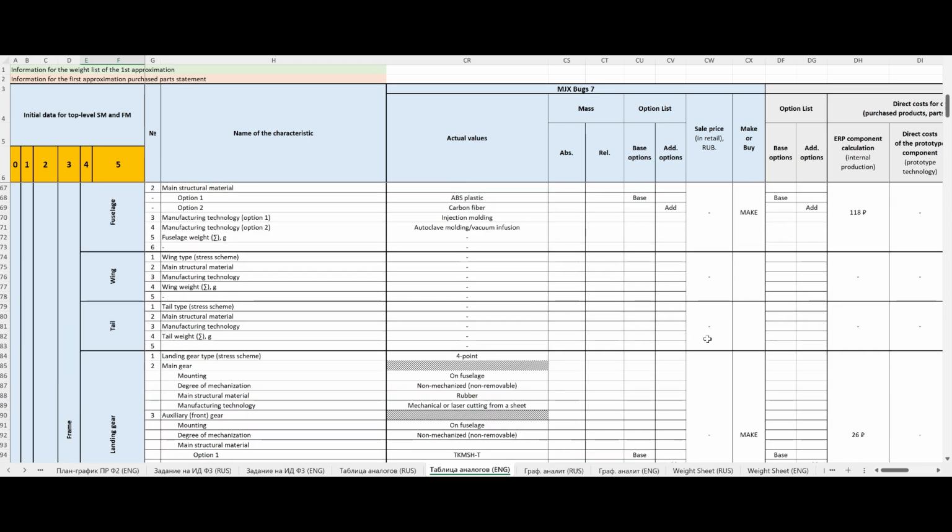With regard to the first method, the most obvious example is the widely used formula for the statistical determination of the payload of unmanned aircraft vehicles. We are talking about a statistical ratio according to which the payload mass is about 0.22 to 0.27 of the takeoff weight.